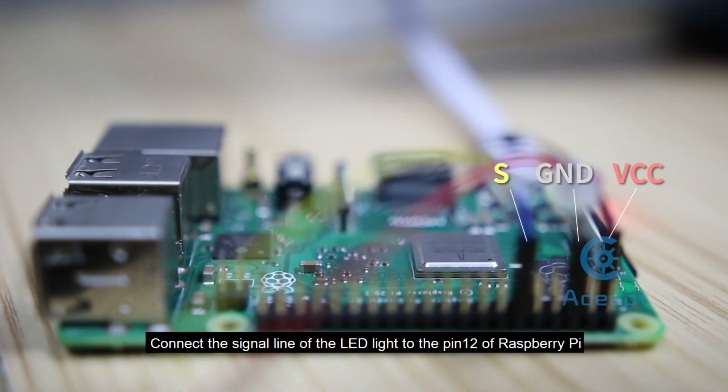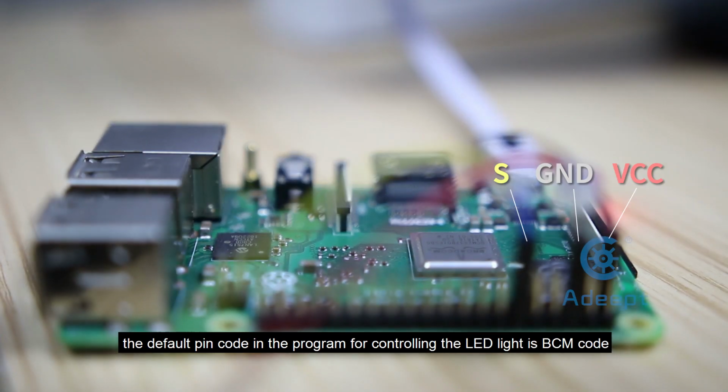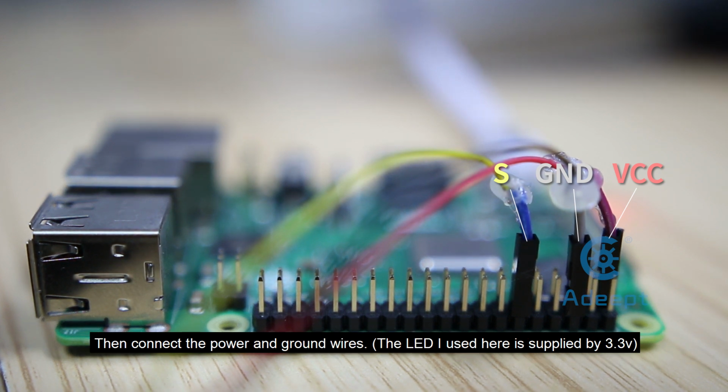Connect the signal line of the LED light to pin 12 of the Raspberry Pi, which is the BCM-coded pin 18. The default pin code in the program for controlling the LED light is BCM code. Then connect the power and ground wires.